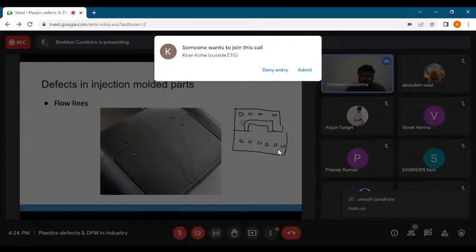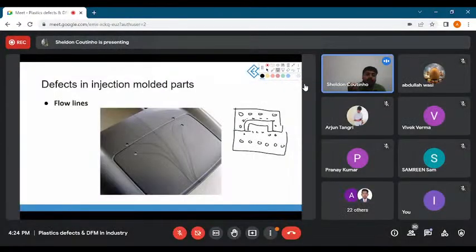So how do you dodge that? By adding something similar to band heaters, if you remember, which provides even heating. Actually, not even heating. You want something that will keep the plastic warm. When I say warm, you want the plastic to be in a semi-solid format, something like a slurry, a very, very thick soup. You do not want it to be completely molten, and you do not want it to solidify.